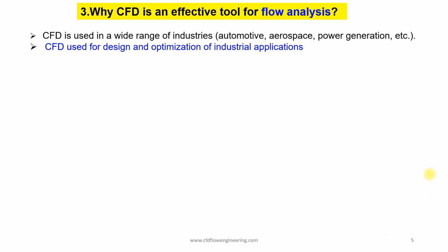They are based on formulas, and formulas are based on assumptions. For example, a convective heat transfer correlation is applicable for 2D flow, but this formula cannot be used for 3D applications.